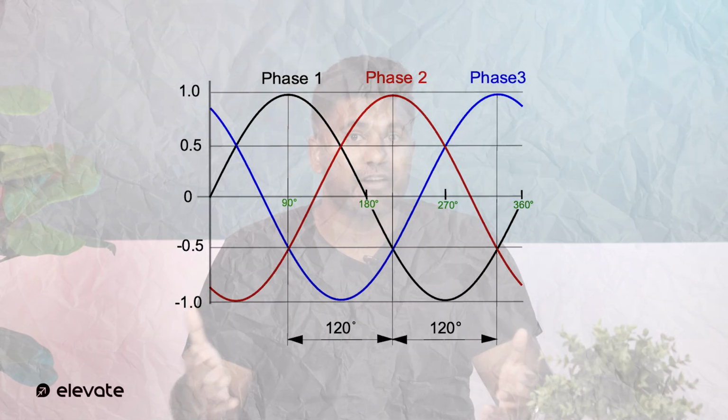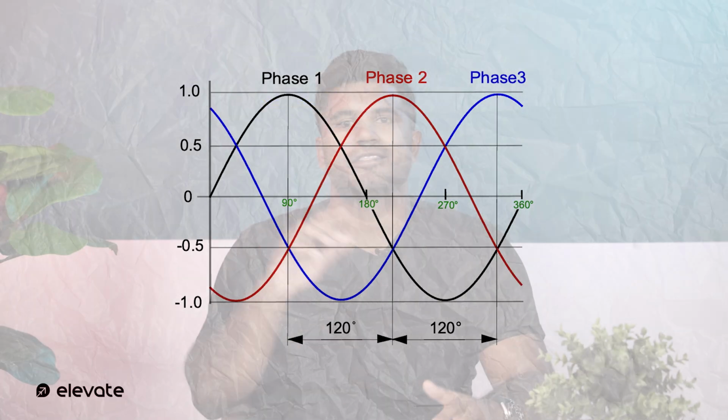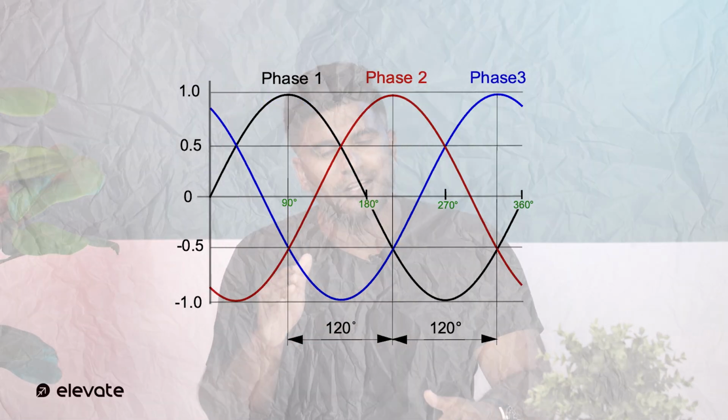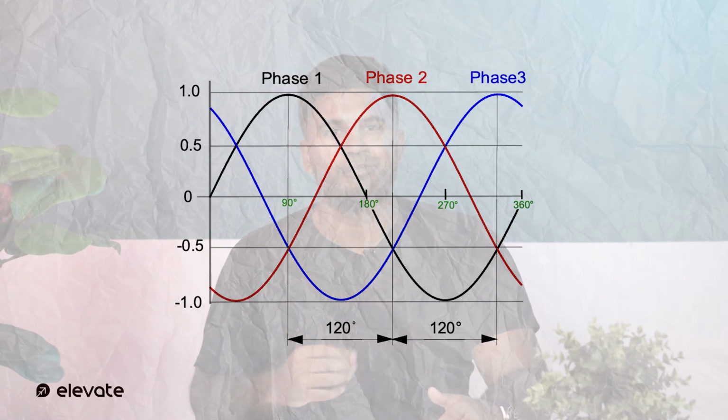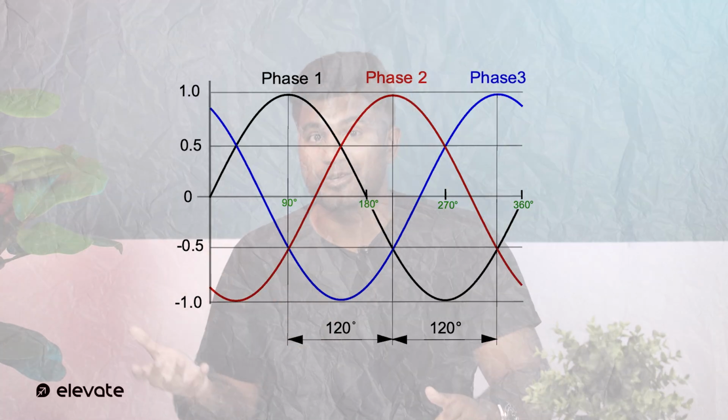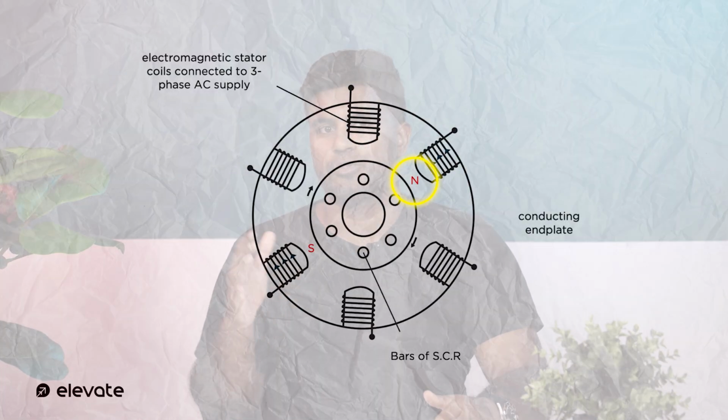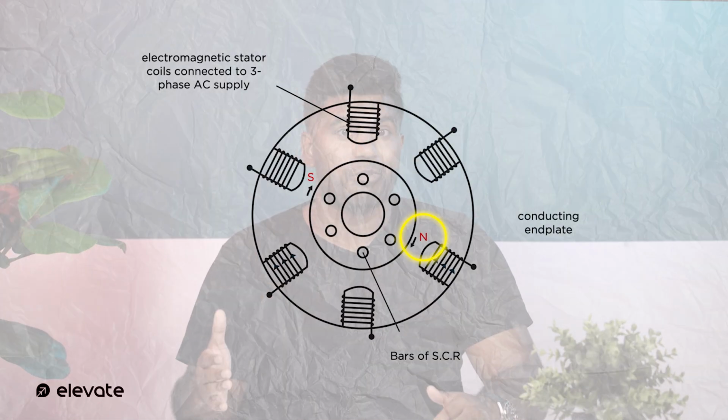Then as seen in the graph, just as phase 1 starts to experience a reversal of current, coil 2 then reaches the polarity that coil 1 was just a minute ago, i.e. an effective north pole. And moments later, the north pole shifts again. So you can see how the stationary coils are creating a rotating magnetic field, all whilst having no moving parts.